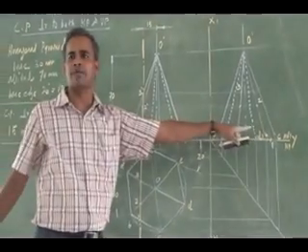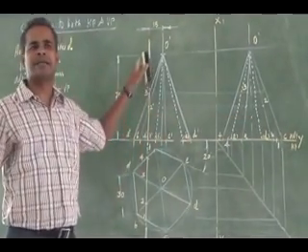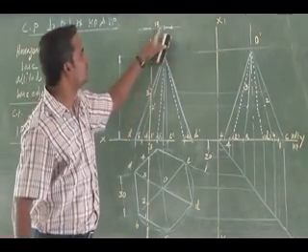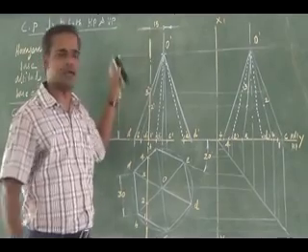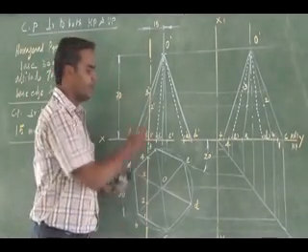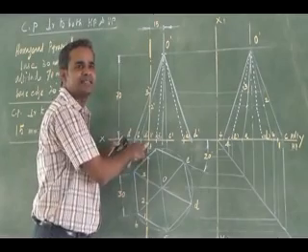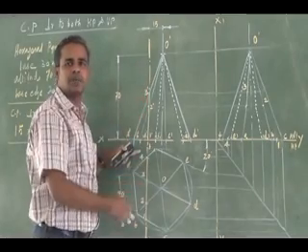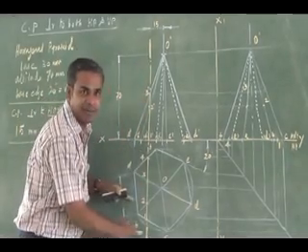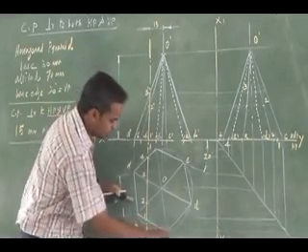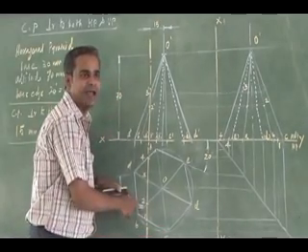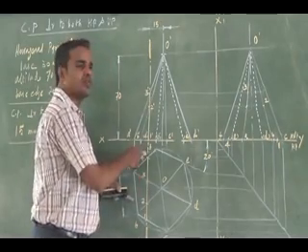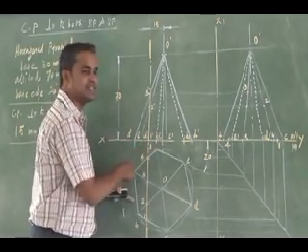So since I am drawing a left side view, I am representing the cutting plane in both the front view and top view to the left side of the axis, that is 15 mm away from the axis to the left side. So I have represented it. See here, when I have marked the cutting points, the base will have two cutting points, then it cuts two slant edges. So two more cutting points, totally four cutting points. You mark the cutting points in the top view in order from the bottom. This is a visible base edge, then it cuts the slant edge, then it cuts the slant edge AO, then it goes for another base edge, a hidden base edge, that is AM.